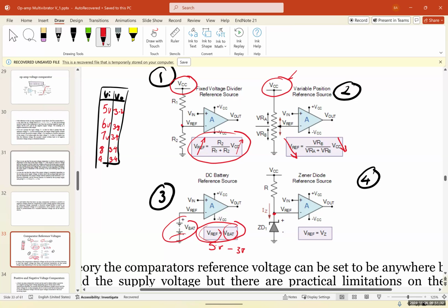And if you connect a sensor, let's say a proximity sensor or a photoresistor or an ultrasound, any type of sensor, obstacle detection sensor. Imagine you have an ultrasound sensor. First, it's giving you an alarm at 5 feet. When the voltage drops, now it's giving you an alarm at 3 feet. Sometimes it's going to be dangerous.